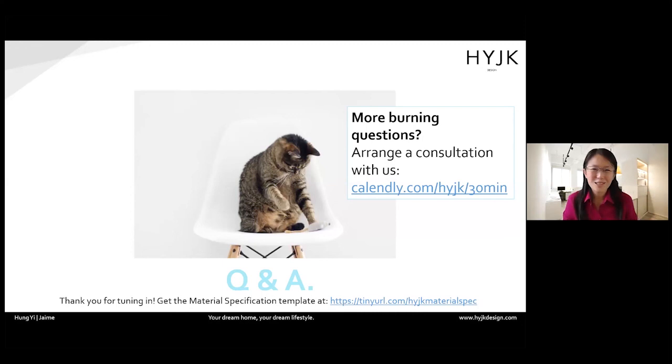But you will not have problems like termites, and you won't have so much expansion and contraction problems. You would still have some with vinyl, as with any material, but not as bad as engineered wood. And of course, solid wood would generally have the most problems, depending on what kind of solid wood you select. Things like Burmese teak, which are very good for tropical countries and better for humidity, will perform a bit differently.